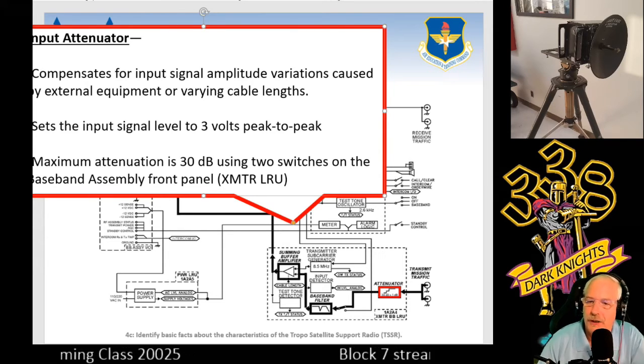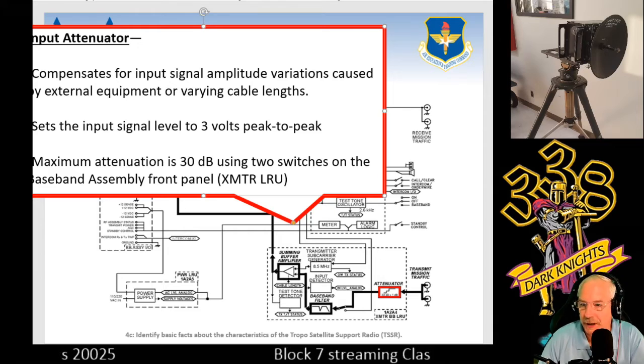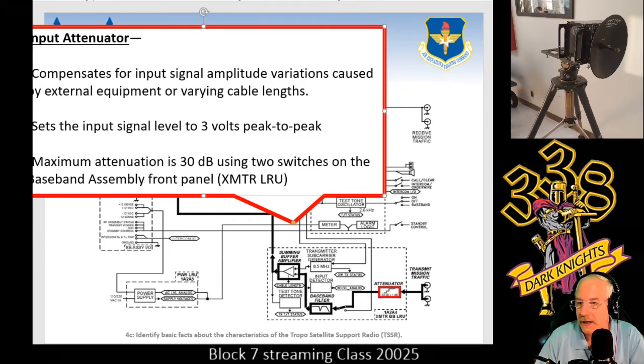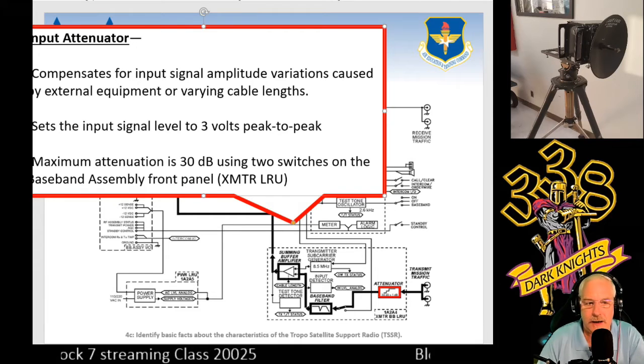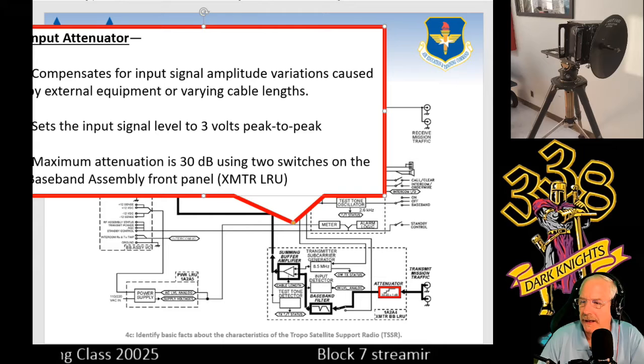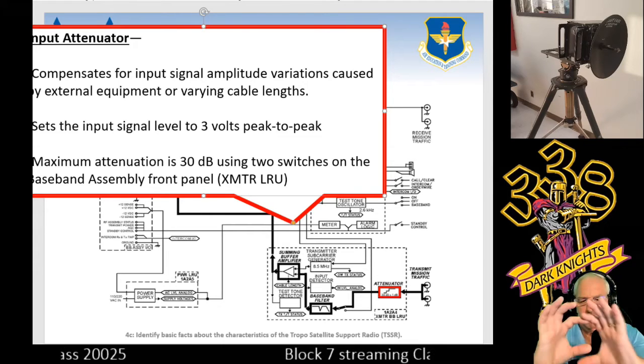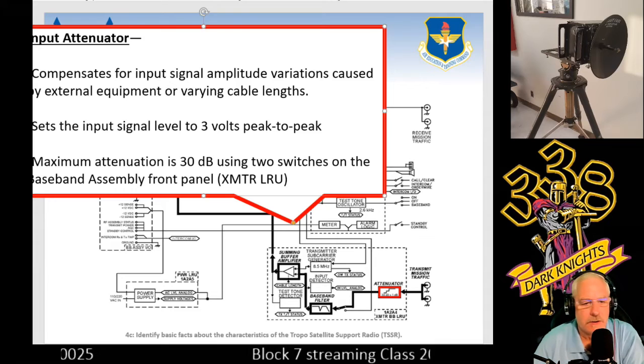In other words, you are putting a multiplexer aggregate signal in there, or mission bit stream. In this case, it says transmit mission traffic. It is a connector on it. It'll say data. There's 2 places that it will have if you're doing fiber optics. There are a couple BNC cables on the back of it, and this particular one, since we're just going with the data circuit itself, is I think like a 30 or 40 pin connector that has a Loctite on it. It's probably about that big, that gets onto the back of the baseband.